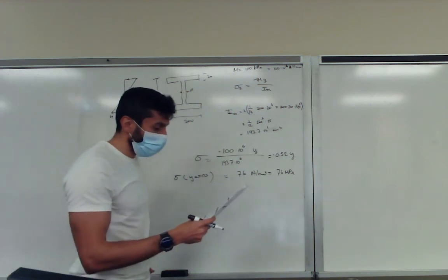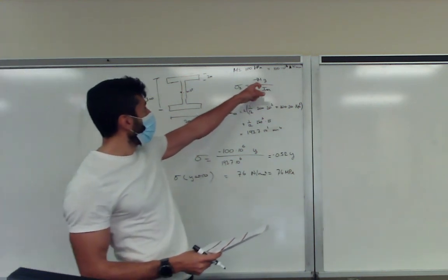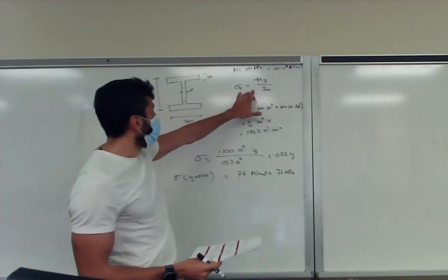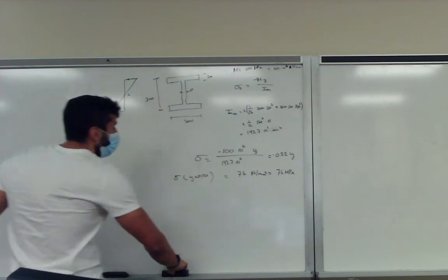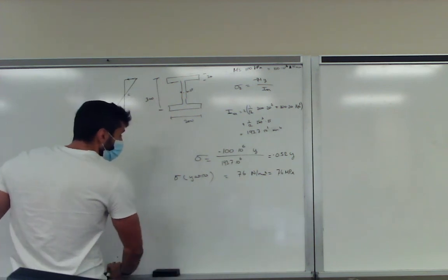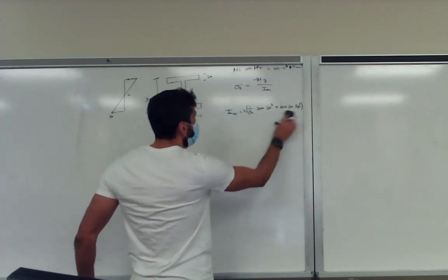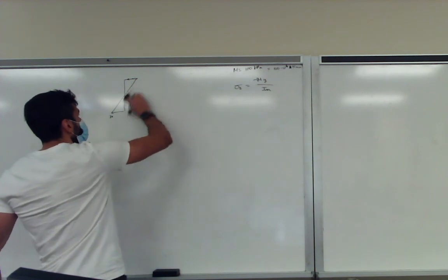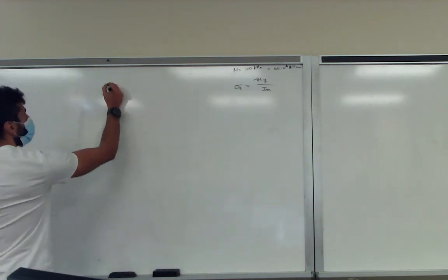And it's important to say a couple of more things about it. So far, we only assumed one bending moment. And if you noticed, I went from I to Ixx. So the reason for that is we only have looked at bending around basically one axis. And that's around your x-axis. And because you're looking at bending around the x-axis, you need moment of inertia around x.